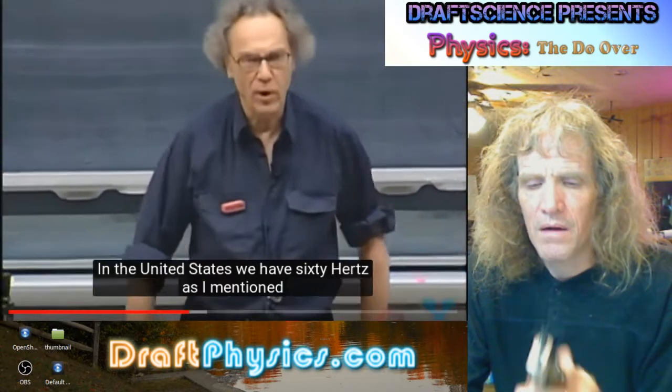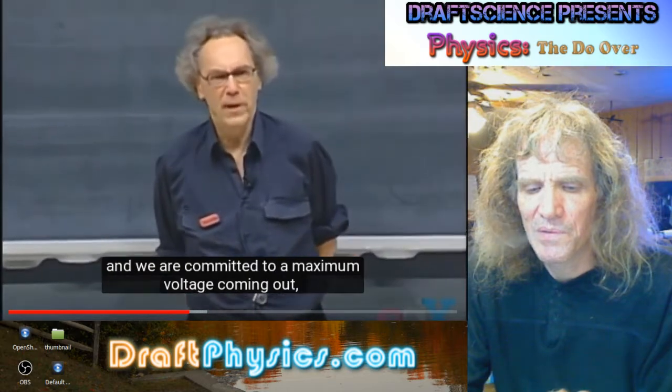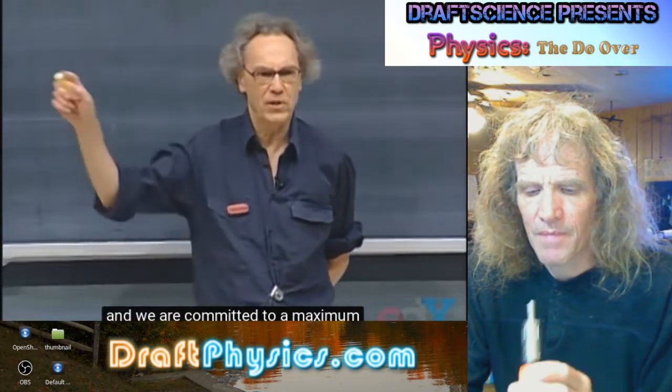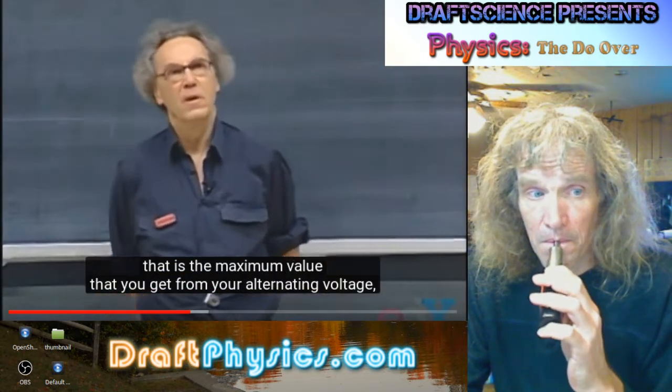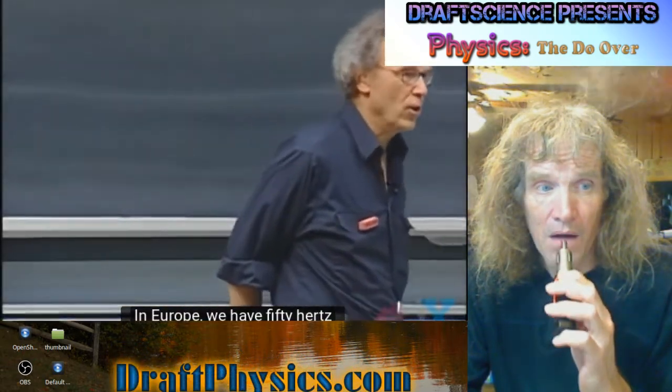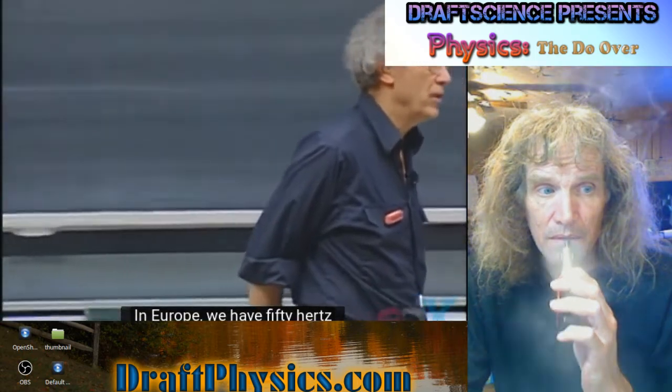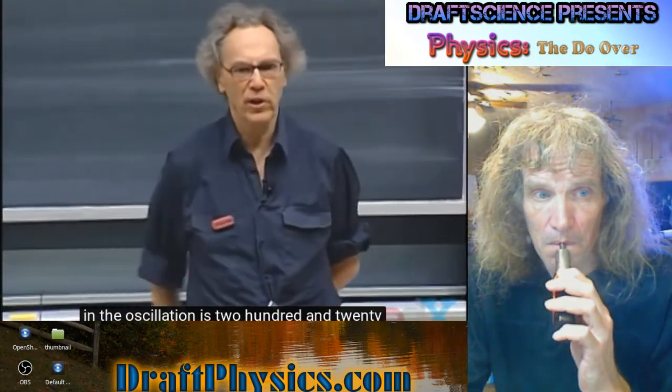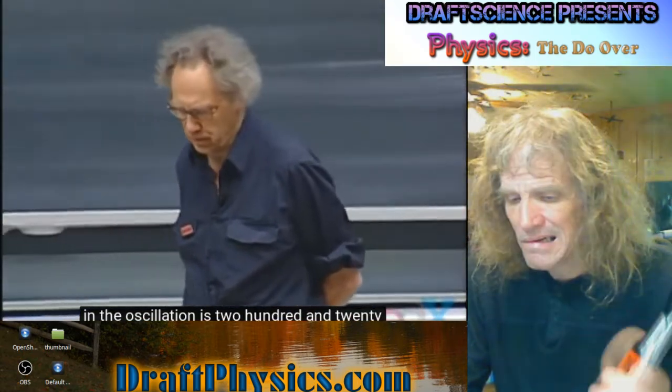In the United States, we have 60 hertz, as I mentioned, and the maximum voltage that you get from the alternating voltage is 110 times the square root of 2 volts, and we call that 110 volts. In Europe, we have 50 hertz, and the maximum voltage in the oscillation is 220 times the square root of 2.